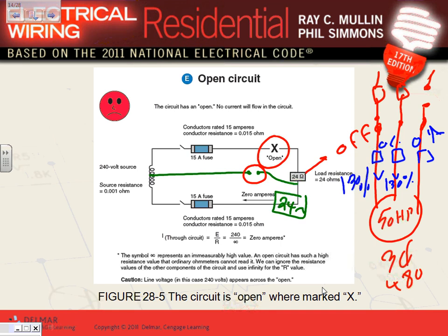Two things happen. If you allow this overloading to continue, you're going to burn your equipment. Overload because of open circuit. If smart enough, we put overloads, guys. You've been sizing overloads. So this overload will see that there is a 30% increase on this phase, and within a minute or so, trips open and saves your motor from burning. Any question, guys, about the open circuit? So with an open circuit, things don't work if it's single phase. If it's three phase, things could burn too. Bad news. Any question about these 5 conditions? Open circuit, short circuit, ground fault, normal, and overload.